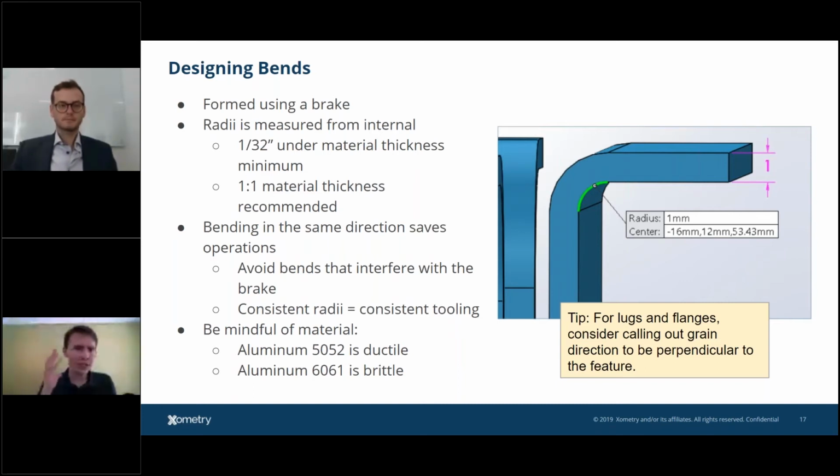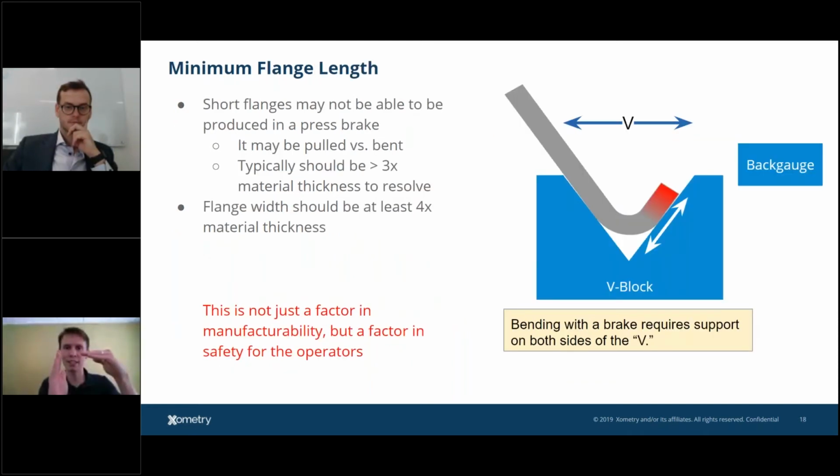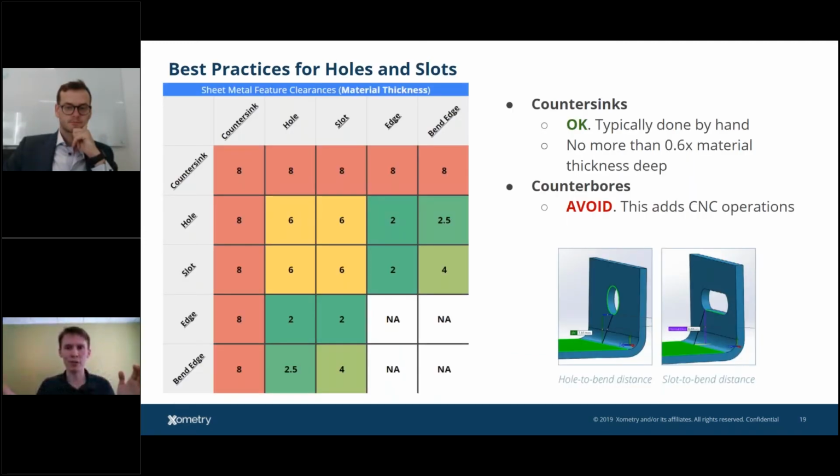So it's all about the bends with sheet metal. It's all about bending, forming, creating the best out of your designs. If you imagine taking a sheet of paper, cutting a hole in that sheet of paper, and bending right in the middle of the hole, you'll probably see that the edges of those holes are going to flare outwards. If you start rotating that paper where that hole is and getting right at where the bend's right at the edge of that hole, you'll see it creates a little lower lip. Exact same thing happens in metal.